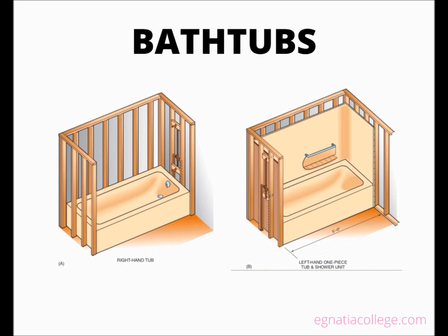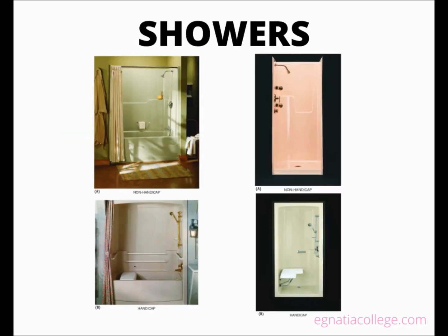Showers. A shower is considered to be a fixture. Shower units are installed during the rough-in phase. Many homes have tile shower bases and walls, in which case the plumber installs the drain, water piping, and faucet.